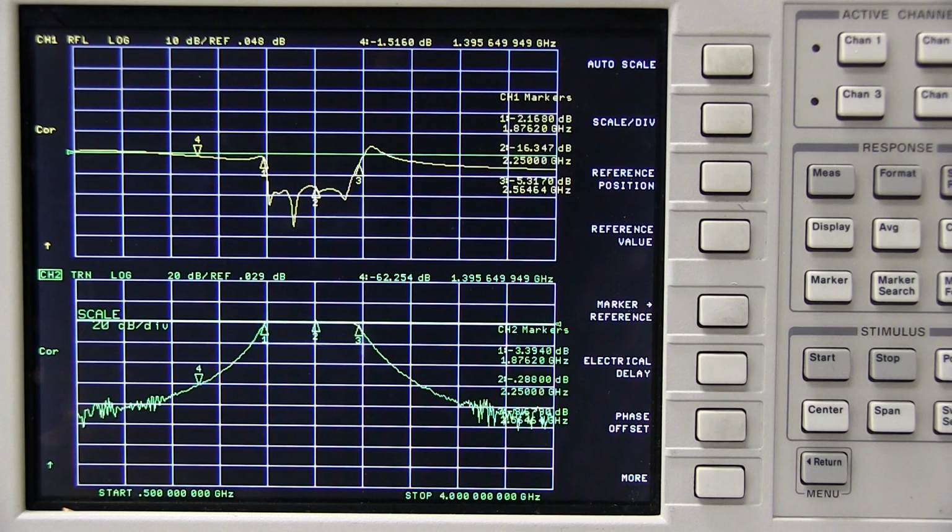We'll do some more advanced measurements on a filter where we can see an even broader band, and you'll be able to see what happens very far out of band. There's things called comebacks and other things where you really can't expect the filter to filter very, very far out of band for certain designs.